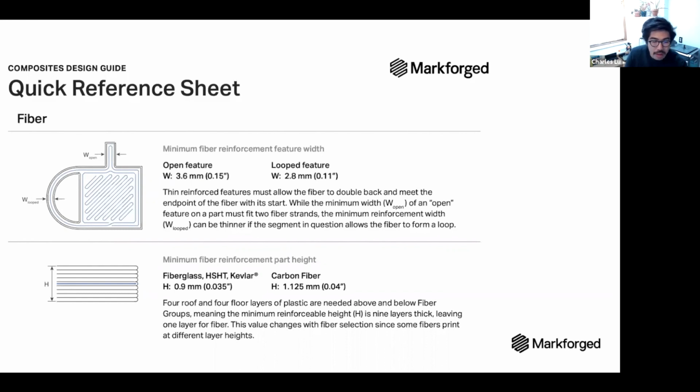Do you need to dry the nylon before printing? An honest attendee asks. You do not. Our material comes pre-dried and sealed in an aluminized bag. So you just load it into a dry box, which you keep the Onyx in, and you print out of the dry box. So you don't need to pre-dry your material.